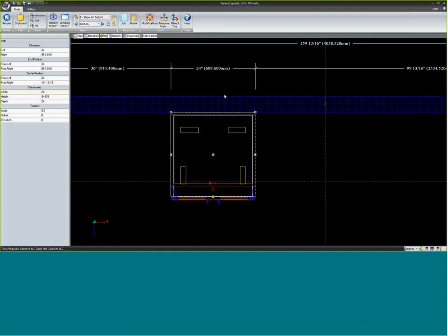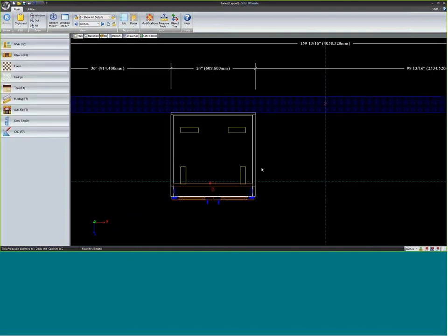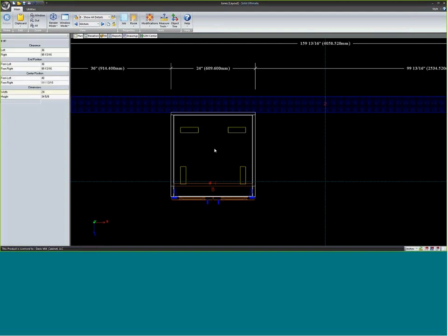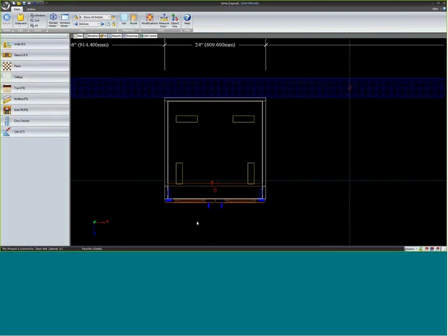The problem with that is that the case box is fine. Our CNC machines cut out all of our case parts, and it can go down to thousandths of an inch and be just fine. The problem comes into play when we talk about solid wood parts like doors or drawer boxes. Those parts are cut by a person reading a tape measure, and so it gets very difficult.